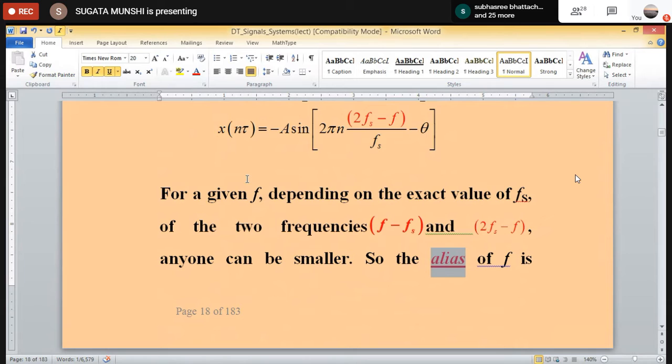That this sampled data signal is not preserving the frequency information of the original analog signal, this phenomenon is called aliasing. Aliasing is the result of undersampling. What is meant by undersampling? Sampling at a frequency that is less than the minimum required.